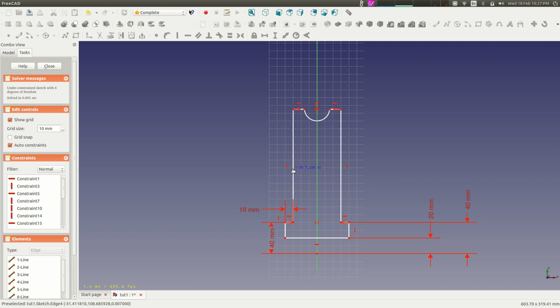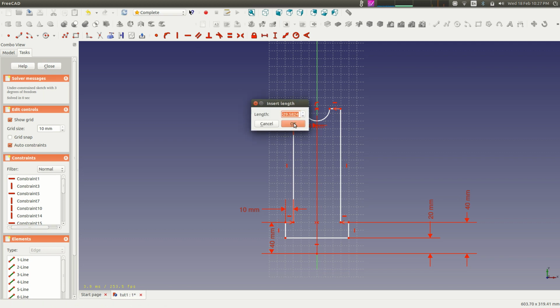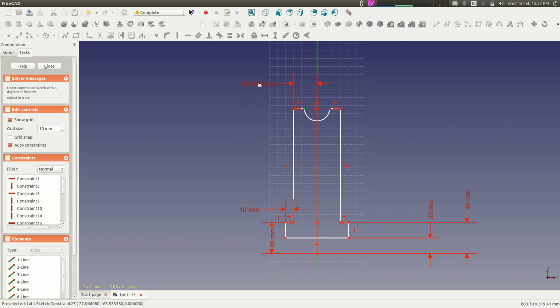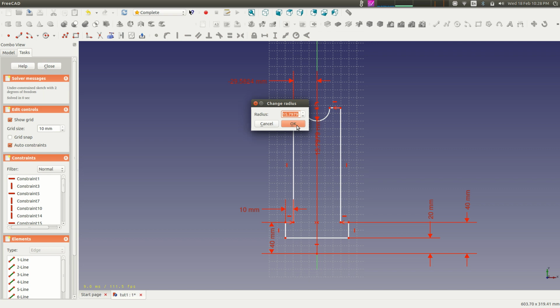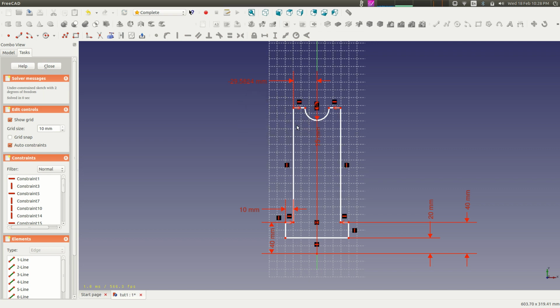So we're still missing a few things. Obviously, the width of this is not defined, and you can kind of tell because I'm moving it around. So I'm going to define a width here. And there are negative coordinates depending on how you define it, because I guess it is dependent on a Cartesian system. So now you see that I do that, I can't change the width anymore. So to define diameters, instead of using the dimensional tools, you can use the tool to define a radius. Let's go 15 there, some nice round numbers.